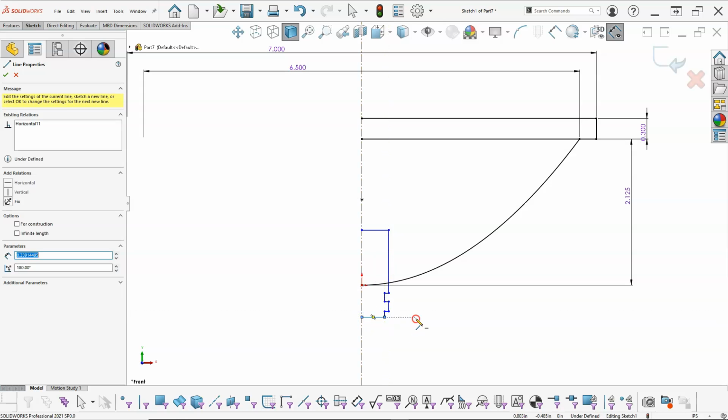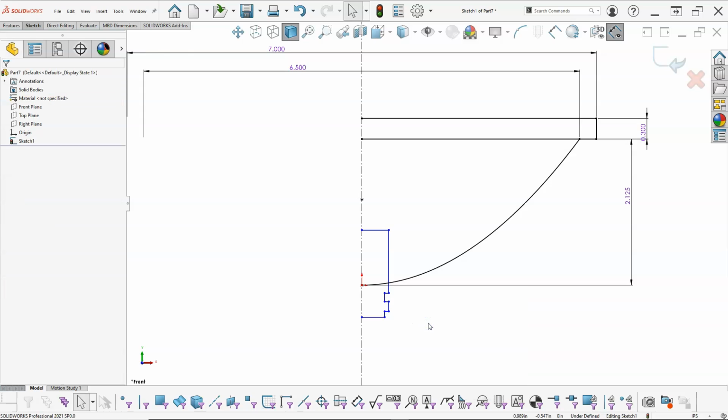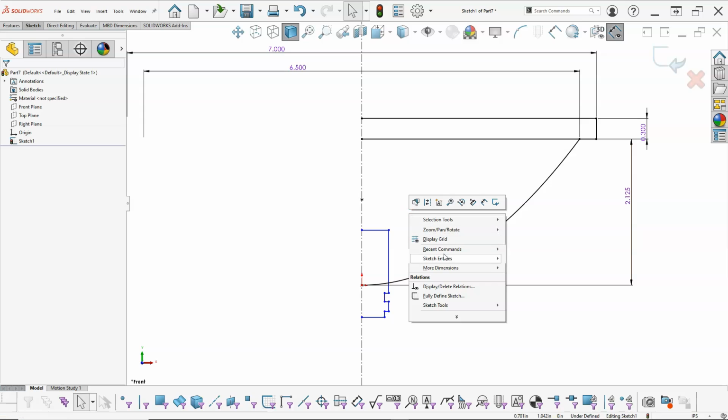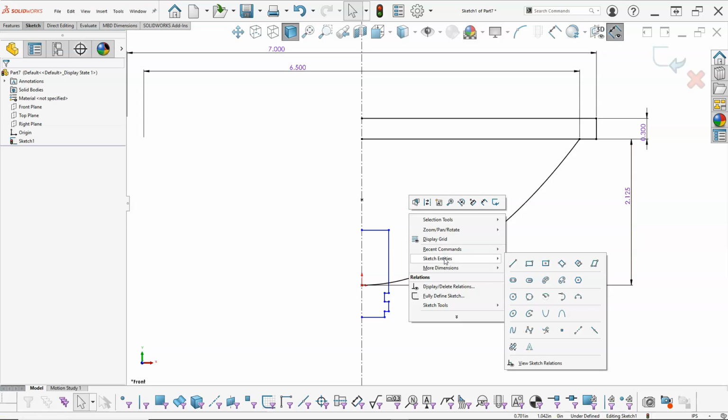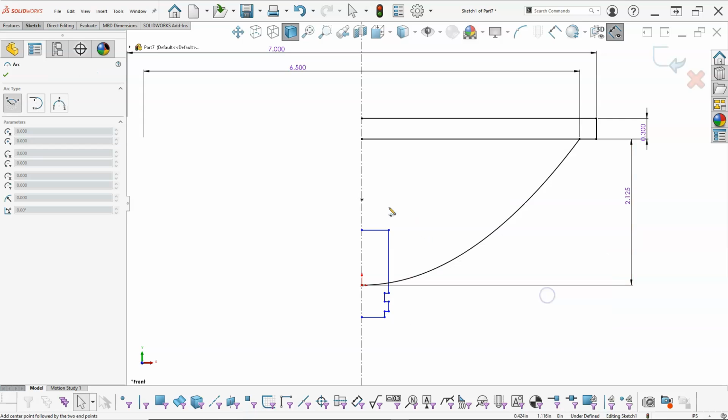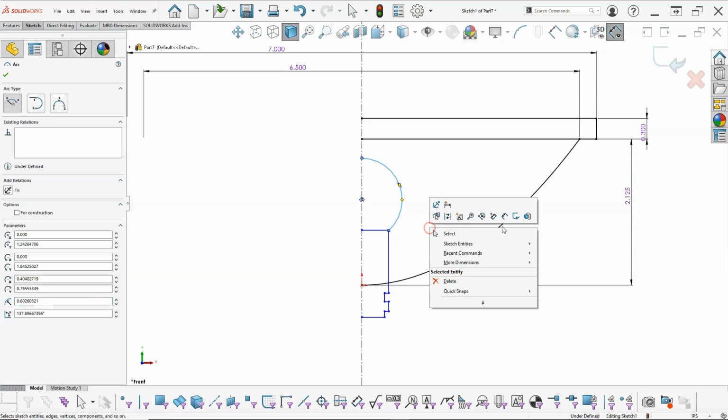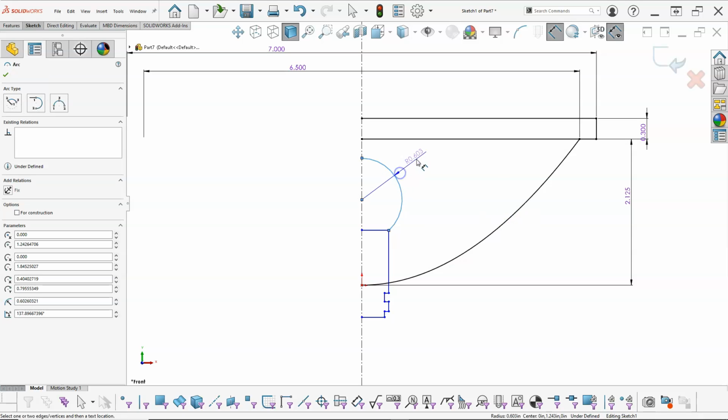And pretty much the last pin or whatever it ends up being would probably be a separate extrude, but we'll go ahead and treat it out here. So bring it back around, attach it, and let's start applying some dimensions.